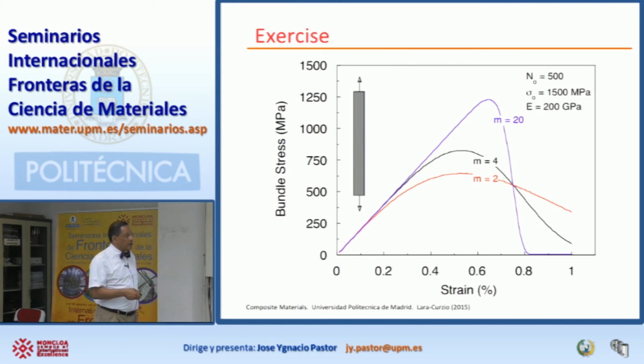The fibers are brittle. The matrix is brittle. The combination of brittle with brittle plus some interfaces will give you tough behavior. Okay? And this is really the interest in using these materials. They are ceramic, so they can operate at high temperatures. And now we have shown a way to develop materials that are tough, that can absorb a lot of energy for a specific engineering application.